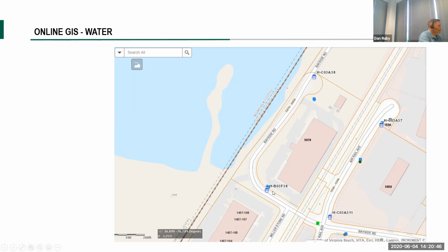So at least you've got an idea if there's some water. If there are fire hydrants on this line, you know you've got a half decent sized line. But to get the missing information on where the water line generally is and what size it is, that might involve a call down to the city, to somebody in public utilities, or a trip down to the city. The City of Virginia Beach has a couple of kiosks available to the public where you just go into the building and pull up this information, and there's additional information there than even what's on the website with respect to water mains.